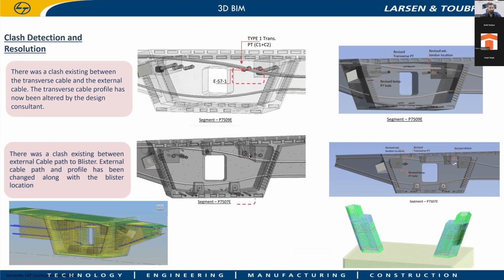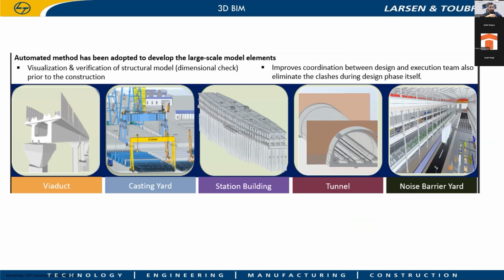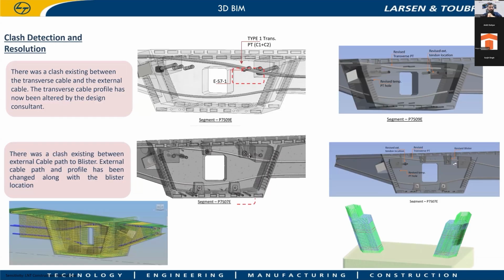We do this in detail in the 3D BIM environment, where we create a proper 3D model at LOD 400 level for all the reinforcements, and we also bring in a model of the tendons, so that interface clash checks and the like can be done as part of coordination in 3D BIM. So reinforcement and tendons are clash free in that slide. Is that correct? Yes, to ensure that it is clash free. Great.